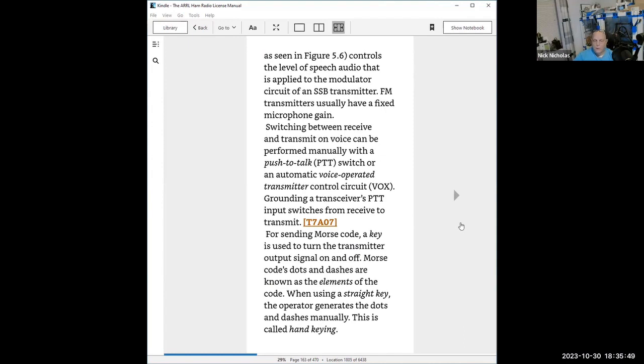Every two-way radio is going to have a circuit for push to talk. Push to talk turns on a microphone circuit, but it also turns off the receiver portion of the radio and turns on the transmitter part. Generally speaking, push to talks nowadays are a completion circuit to ground in the wiring, so that the push to talk switch grounds out the input into the radio, and that engages the circuitry that controls the transmit receive switching, and the transmit power and transmit amplifier coming on.